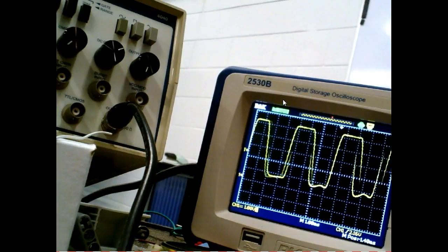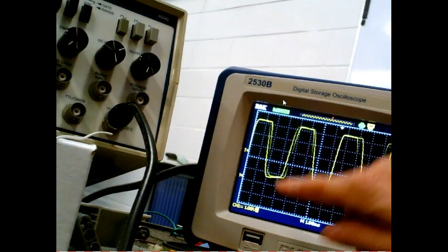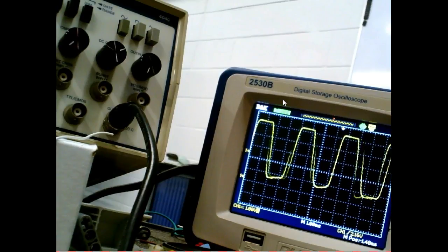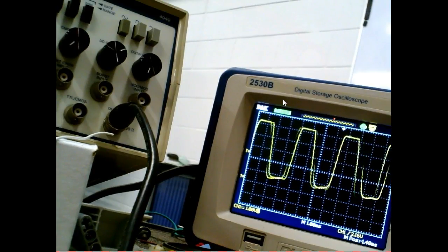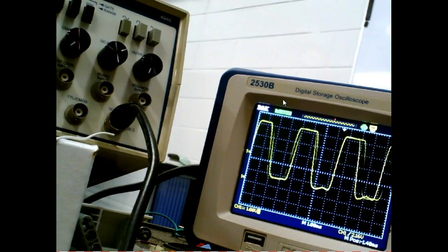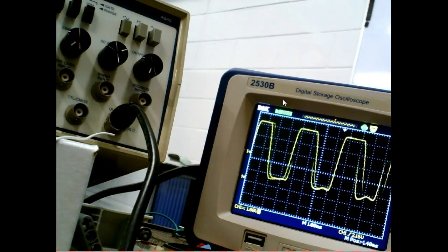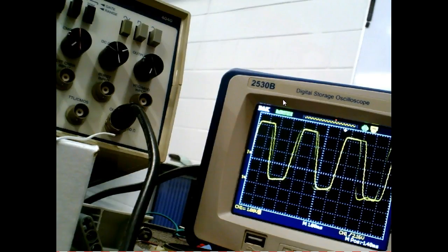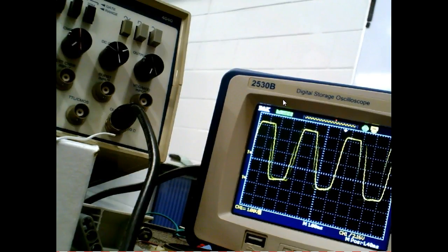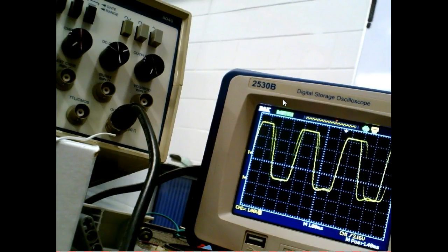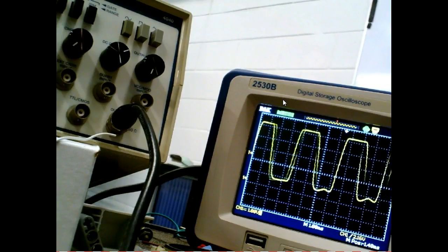So right now, this is an oscilloscope. What's nice about an oscilloscope, and what's the difference between an oscilloscope and a meter, is a meter averages everything. So what you see when you look at a meter, you get an average. An oscilloscope shows you exactly what voltage is there, but the voltage it shows you is relative to time. So in the oscilloscope, not only can we measure voltage with it, we also can measure time. Okay, and of course, revolutions per minute is time, right?